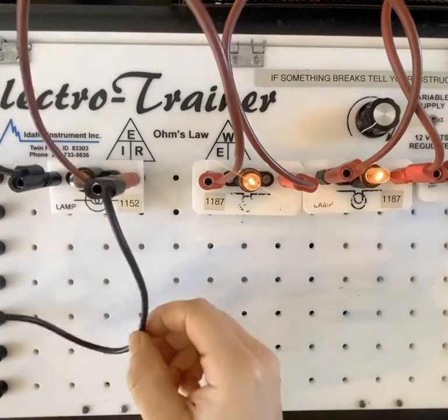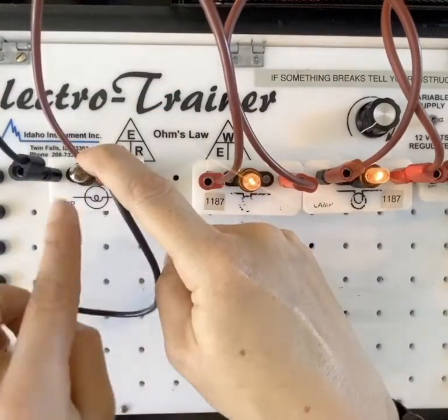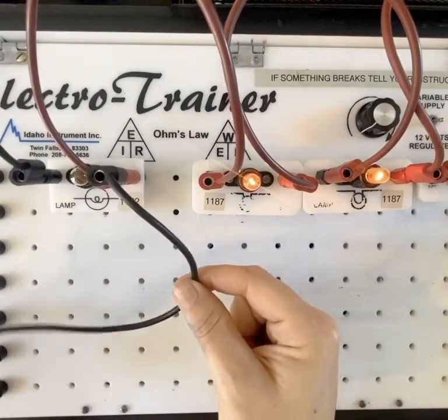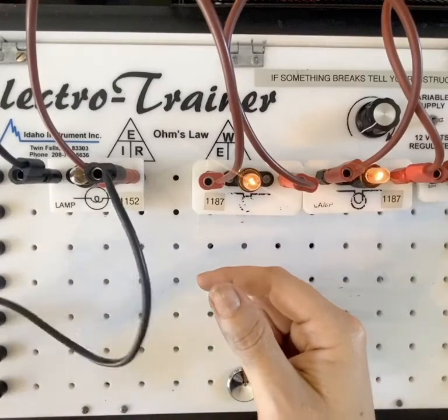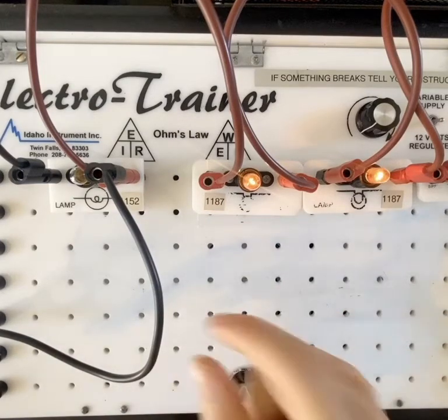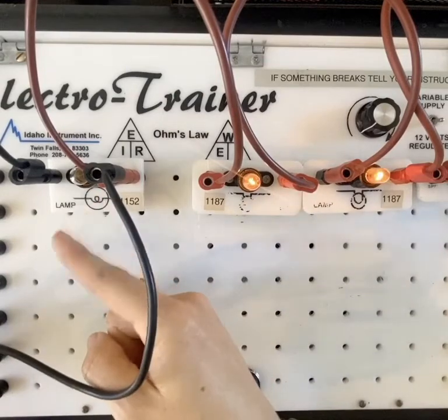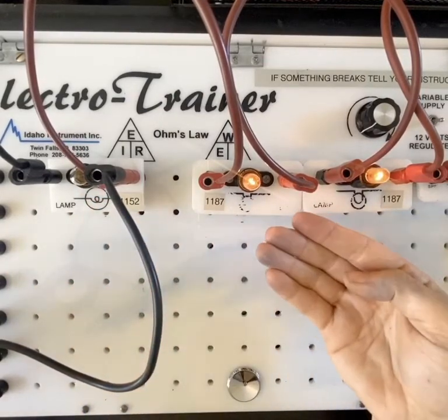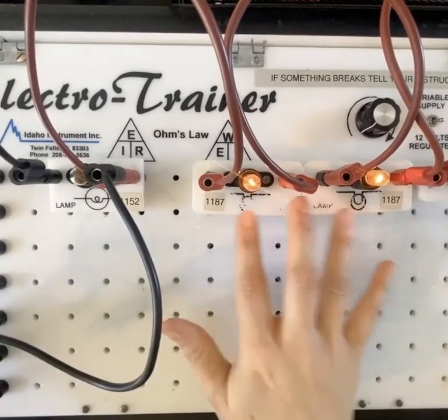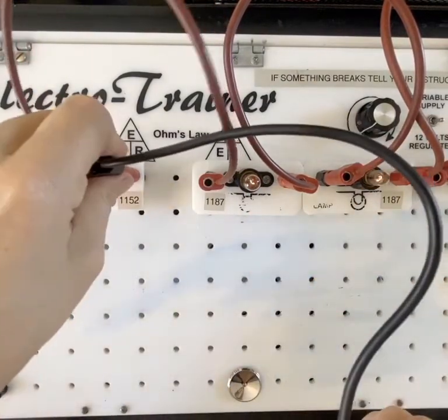This happened because we gave electricity a choice. It is either going to travel to this point, and it's got a fork in the road, and it's either going to go to work and go home. It still has that option, but we gave it the option of taking a shortcut without having to do that extra work through the light bulb and get to go home. And electricity will always find the path of least resistance. And so if anything like that was to happen, that's the result we get. And now because it's bypassing that extra load, our total circuit resistance goes down. These two don't have to share the voltage with the last bulb anymore, and so these get 6 volts each again, and so we see those brighten up a bit. So just a couple of cool little things that we've got going on here.